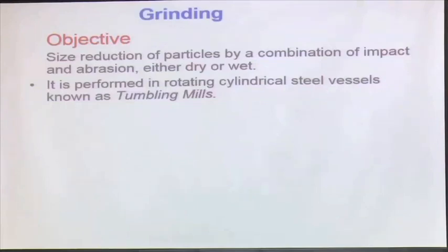You do it by stages. You have crushed it, and what happens when it is becoming finer and finer? The surface area generation is more and more. And which one will consume more energy? Suppose from 100 millimeter to 10 millimeter, or 10 millimeter to 1 millimeter, which one consumes more energy? 10 to 1. Why? That is why when you are going for finer and finer sizes, your energy consumption goes up.